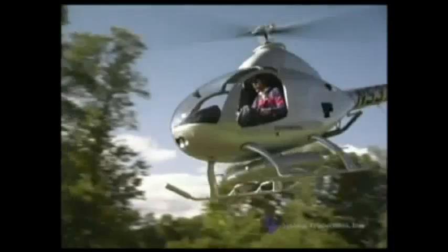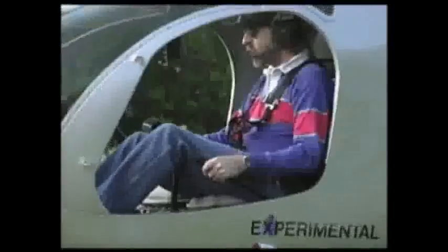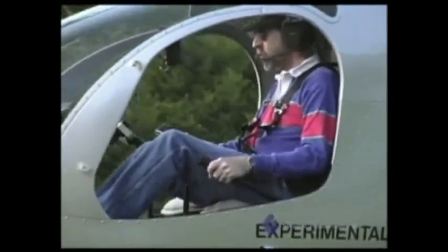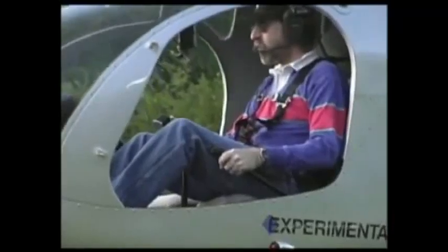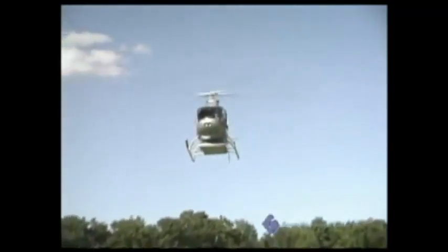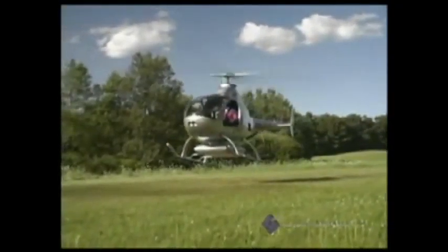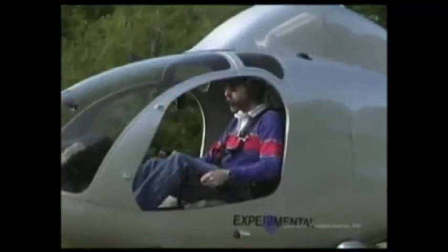But keep in mind that the directional thrust associated with the moving of the cyclic causes the lift component to be reduced. Raising the collective and adding throttle would increase the total rotor thrust and maintain or even increase altitude and speed. To get the helicopter back on the ground, we need to move the cyclic back enough to slow down and stop. Then lower the collective and reduce the throttle to settle onto the ground.